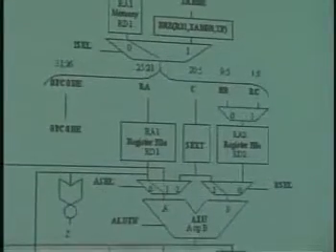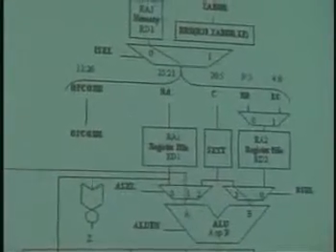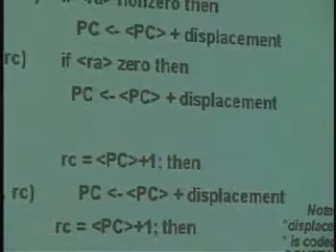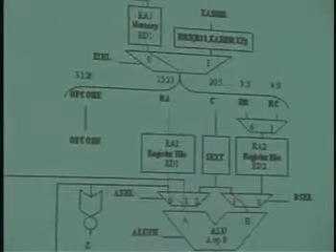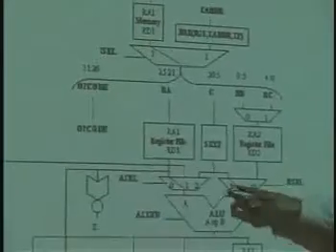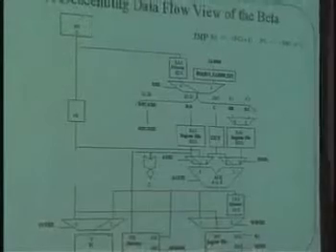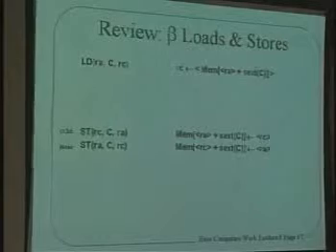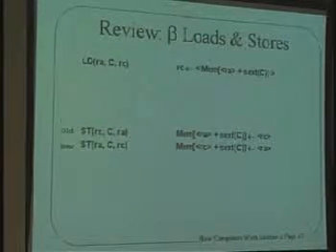And one other change takes place. Instead of there being a conditional, which is down there, you'll see that it may take the left-hand path, which is to not update the PC, or it may take the right-hand path, which is to update the PC. We're always going to update the PC with the addition of contents of RA plus C going out to the PC, because jumps always happen. Okay. Isn't this fun? Okay, we're just about there.